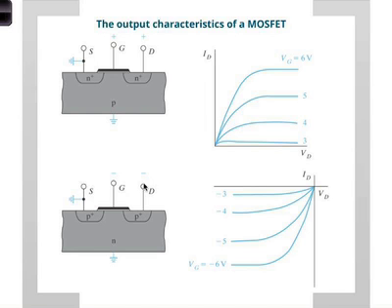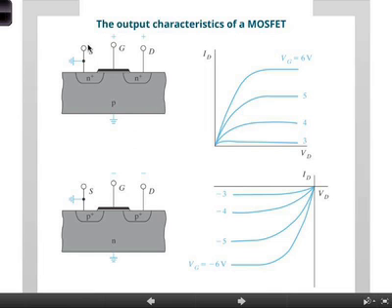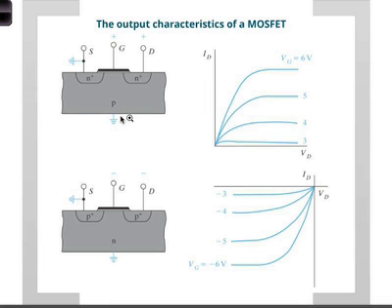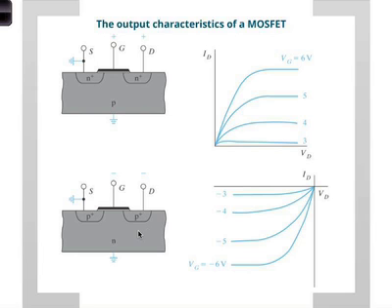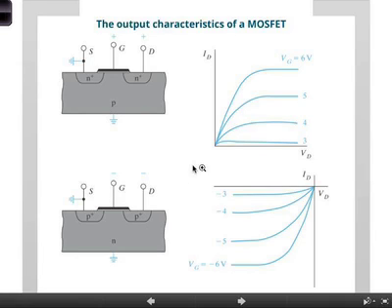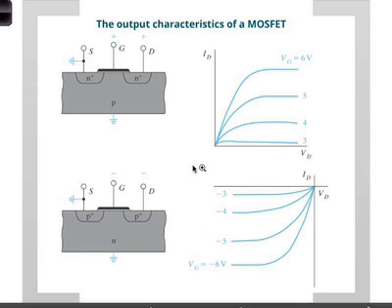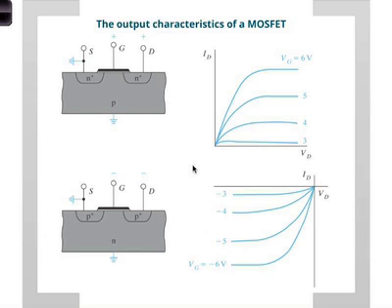The fact is that most silicon wafers used for devices are P-type, which means the N-channel MOSFET is the conventional MOSFET. When you need to make a P-type MOSFET, you have to make an N-type well. We'll talk about that in chapter 9. That's why the drain to source current is always considered positive. That's just a convention. Okay?